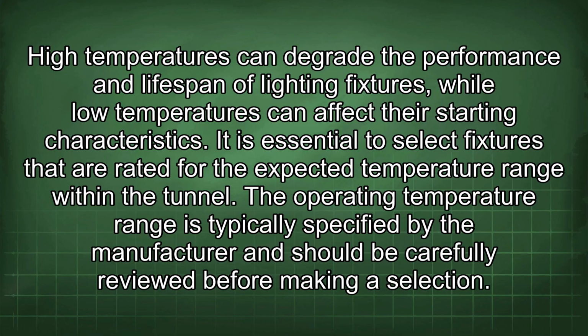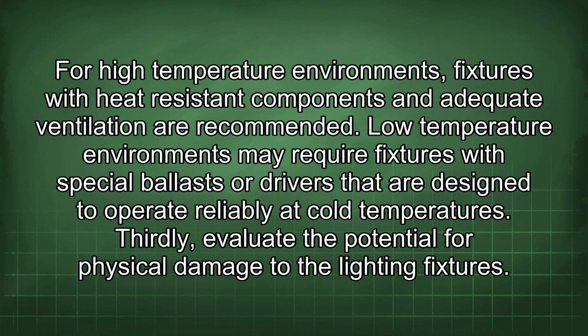The operating temperature range is typically specified by the manufacturer and should be carefully reviewed before making a selection. For high-temperature environments, fixtures with heat-resistant components and adequate ventilation are recommended. Low-temperature environments may require fixtures with special ballasts or drivers that are designed to operate reliably at cold temperatures.